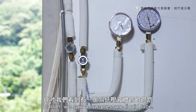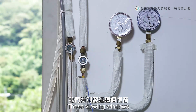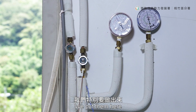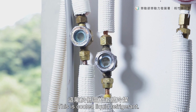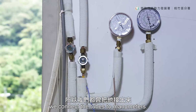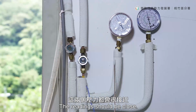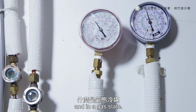Earlier, we saw a low-pressure liquid tube. The other is the low-pressure gas tube. The viewing windows do not exist in normal AC units. We put them here for trainees to see the liquid refrigerant inside. This is cooled liquid refrigerant. It passes through here, absorbs heat in the room, and returns in a state of gas. For training purposes, we connect the tubes to manometers, one for the gas and one for the liquid. The readings should be close. This is to give you a better idea of the refrigerant in a liquid state and in a gas state.